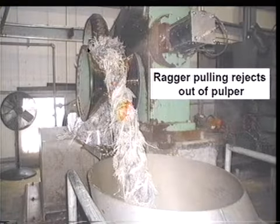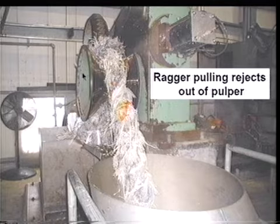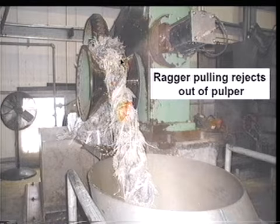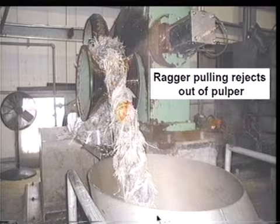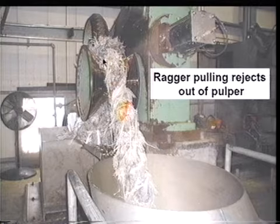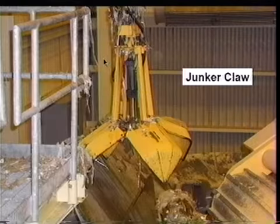Okay, and this shows you again that ragger. Here's the wheel, one of the wheels actually right here, and these wheels are moving in such a manner to move this snake out at a certain velocity so that it gives it enough time for enough wire to wrap on so it's strong enough to be pulled out. A very efficient and clever way to remove contaminants from a pulper.